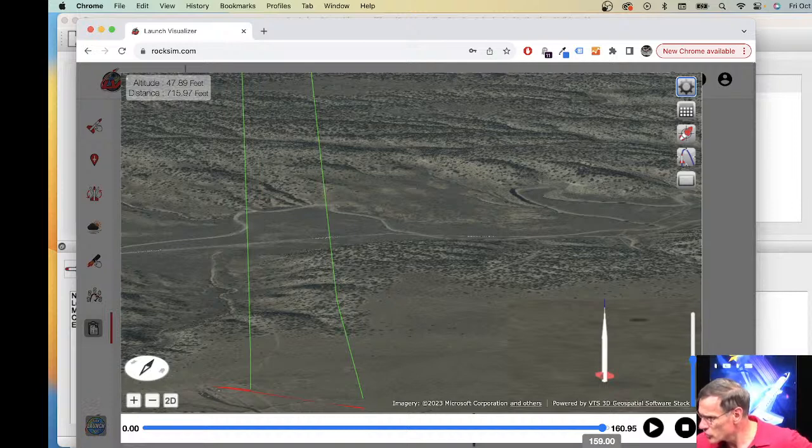Johan says, curious what the main rocket delay will do. When you're doing dual deployment, if this rocket did not go that high and this point here happened before 14 seconds, so it was like 6 plus 14, about 20 seconds into the flight, the ejection charge of the rocket motor is going to blow out.